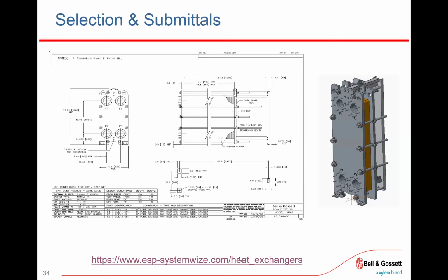I was in tech support and I got a call, and I think it was Mariano back then. What he was doing is he was making these selections for the Packers stadium. And so we were making the selections and we put all of these together, and then come to find out that the local code was requiring double wall for the pools. And these were titanium heat exchangers. I mean, these were really, really, really expensive heat exchangers for this place.